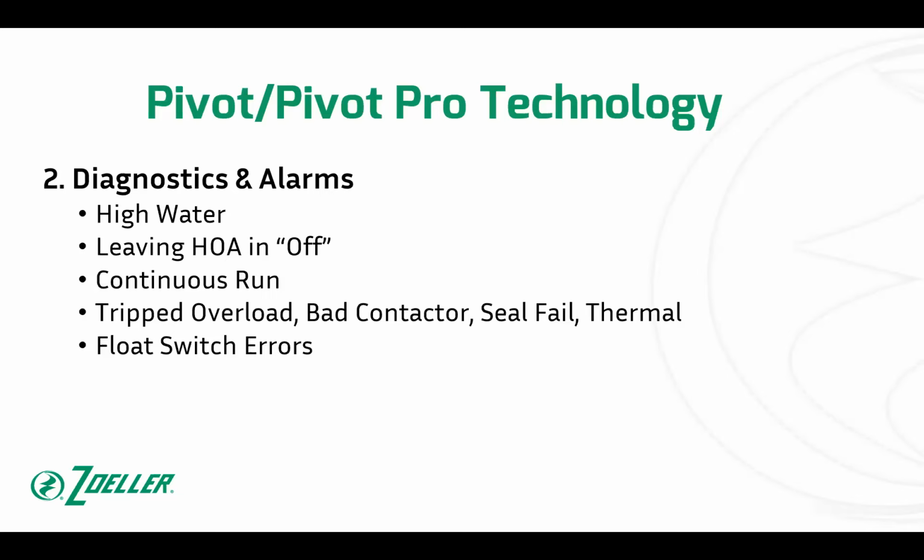When that stop float doesn't come up, and the next float, which would be your lead float in a duplex, when that comes up, guess what happens? The answer is nothing. No pump runs. The water is going to continue to rise. It's going to trigger the high water float. There's going to be an alarm. Hopefully no property damage, but there could be. But that's the first time that somebody knows that there's a stop float issue.